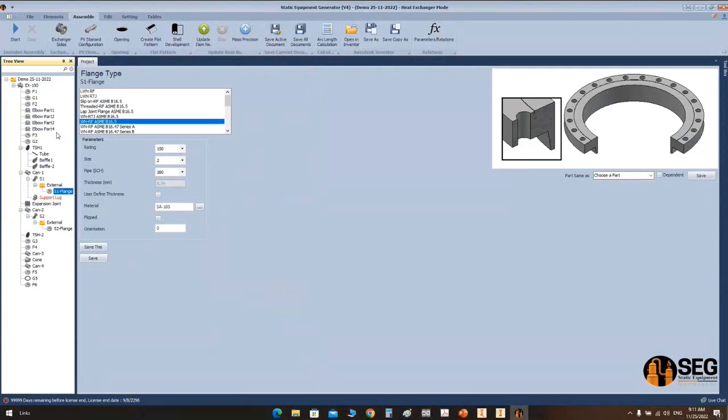The difference between them: the red color means the item is not created on Autodesk Inventor yet, or needs to be updated on Autodesk Inventor. Here, this item is already created, but we need to make an update for the parameters of this item, as there are some parameter changes. So the red color means this item needs to be updated on Autodesk Inventor or is not created on Autodesk Inventor yet. The blue color means this item does not need to be relocated or reassembled again.